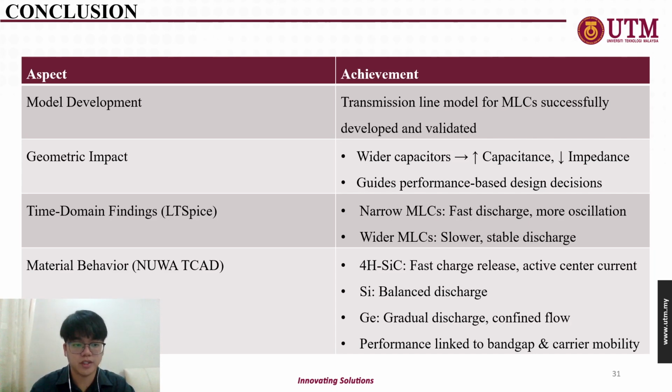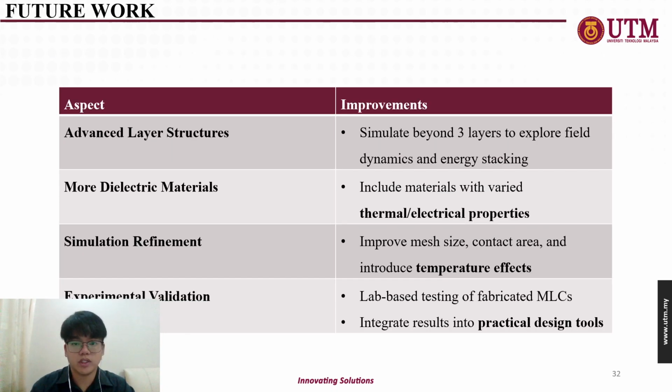Going to material behavior, I will be explaining in the last slide. So all the performance is actually linked to the bandgap and carrier mobility of each material. So in future work, we can do advanced layer structures, which we can simulate beyond 3 layers to explore more field dynamics and energy stacking, and we can also use more dielectric materials with varied thermal or electrical properties. And also we can do simulation refinement, where we can improve the mesh size and the contact area, and introduce temperature effects, and also do experimental validation by doing lab-based testing of fabricated MLC.